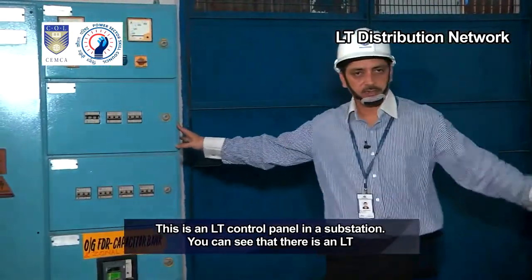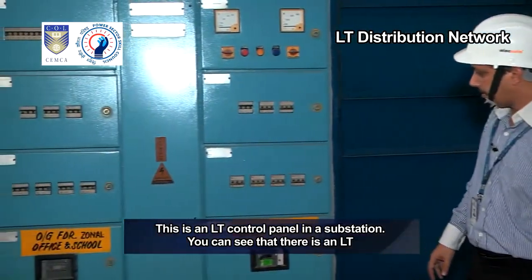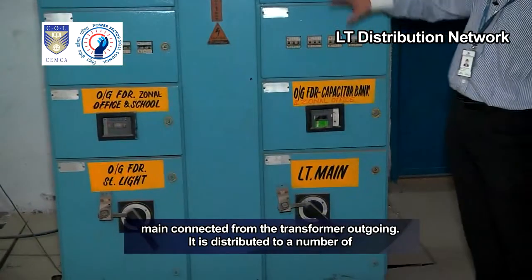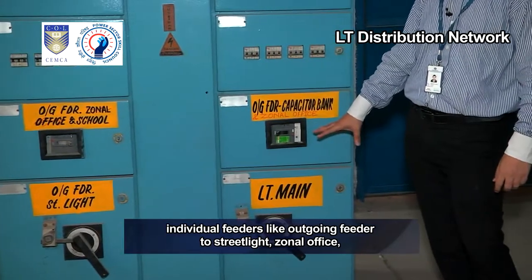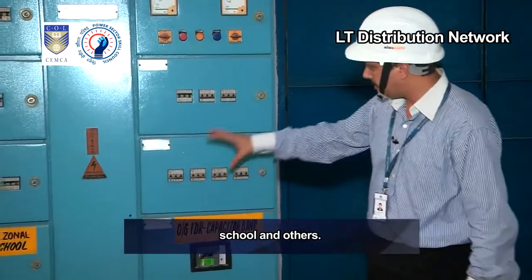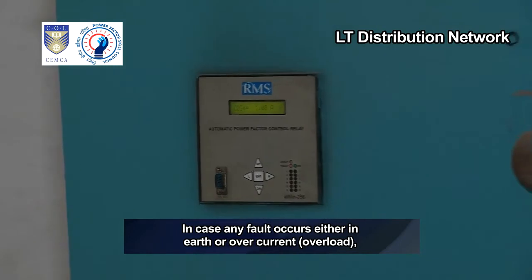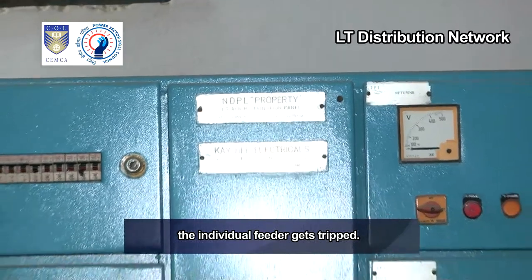This is an LT control panel in a substation. You can see that there is an LT main connected from the transformer outgoing. It is distributed to a number of individual feeders like outgoing feeder to street light, zonal office, school, and others. In case any fault occurs either in earth or overcurrent overload, the individual feeder gets tripped.